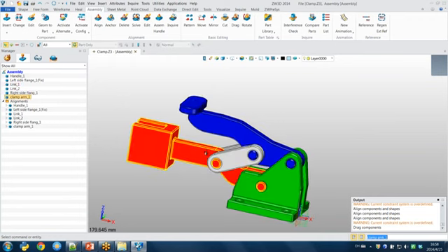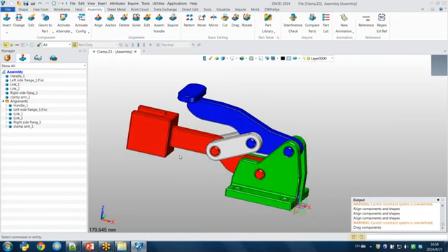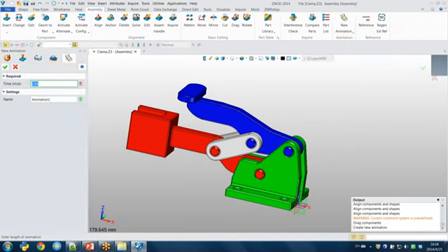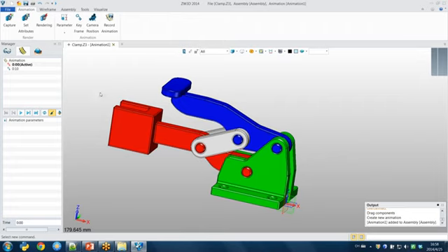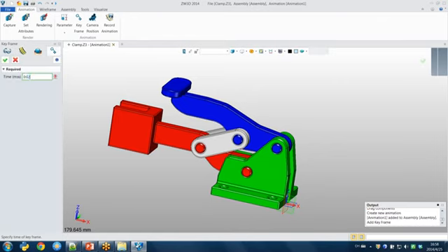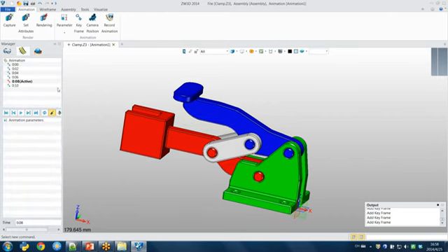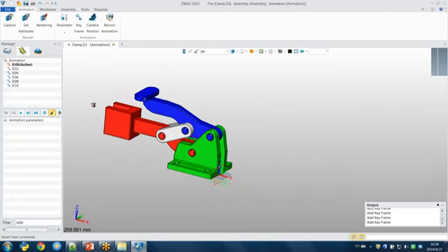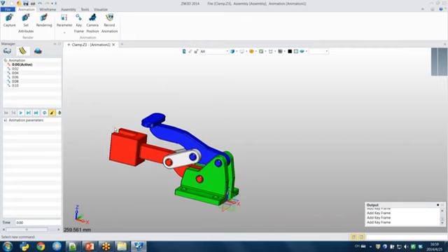So after I finished the assembly design, I would like to make an animation. So how to do the animation? I can use the new animation function to create just a 10 second animation. Press OK. So first I need to insert the keyframes. Second, fourth, 6, 8. That's okay. So then I activate the first frame and put the position.